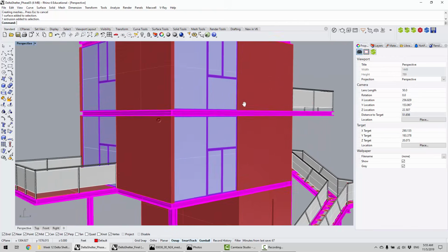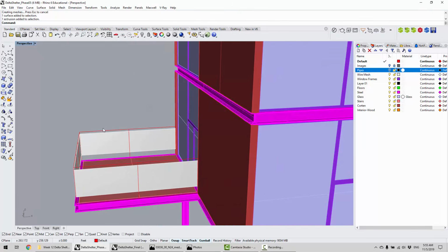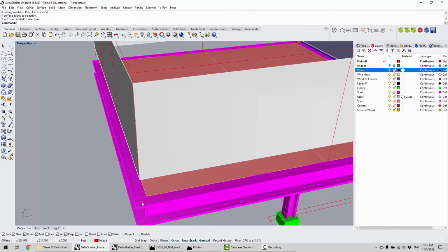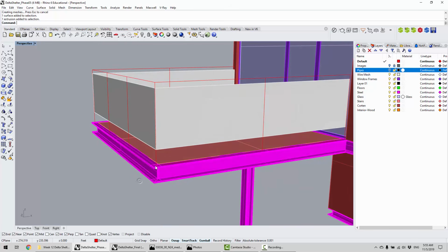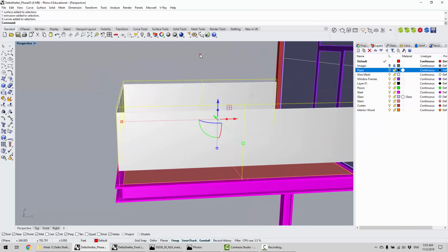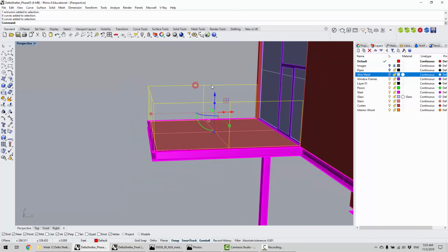But at the same time, I think these pipes, right? Essentially, what I do is I find the center line of this, I trace it, copy it up, and draw these. These are 3 feet in height balustrades, right? And this curve network, I just pipe them. So that gives you an idea of how that works.